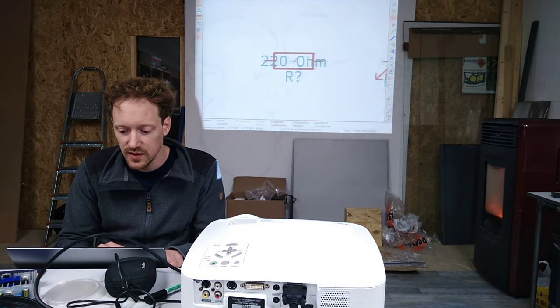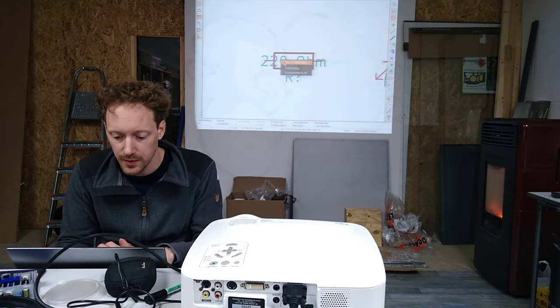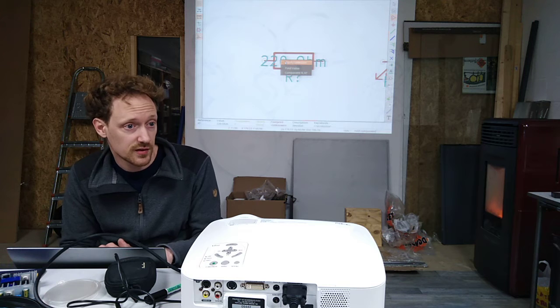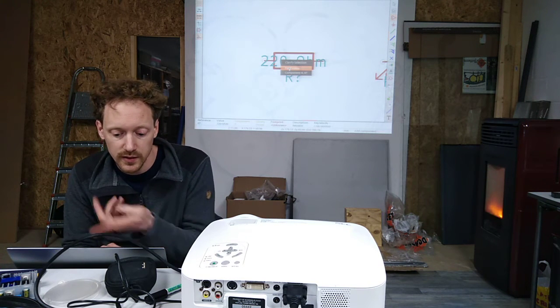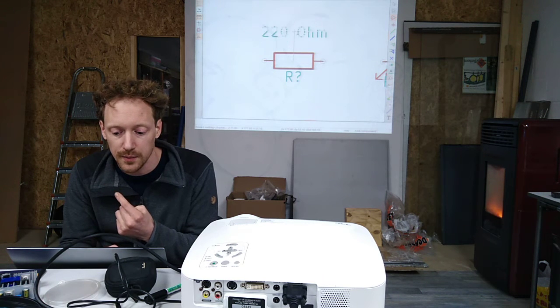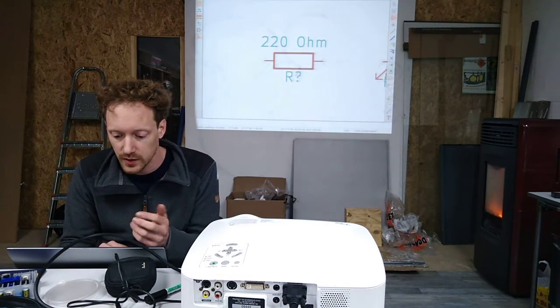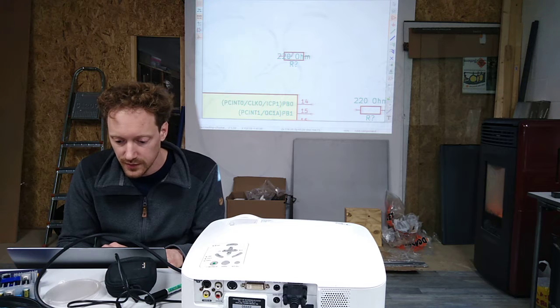Well, you can see that this doesn't print as nicely, but we can just pick up the label. It asks us now to clarify what we are selecting, and I'm choosing the field value now, and I move that a little bit up. And you can see it's still connected to the component. Press enter and we're done. And we're going to do the same for this one.